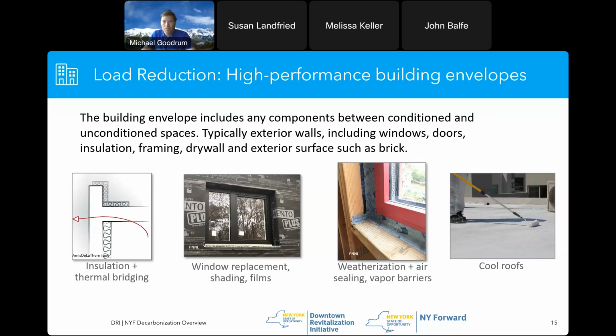And then cool roofs. I know for New York, a lot of the communities are in cooler climates, and so the thought is, well, maybe cool roofs wouldn't be great because you'd want the heat in the winter. There have been some studies that have shown, even in cooler climates, that it still overall saves energy to have cool roofs. They had a study, I think it was done in Minnesota, and it showed that over the course of the year, you still saw energy savings from a cool roof.